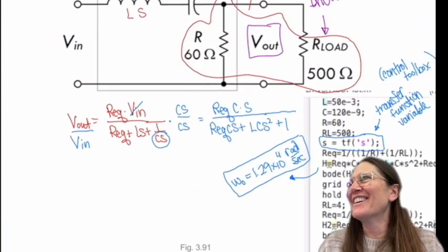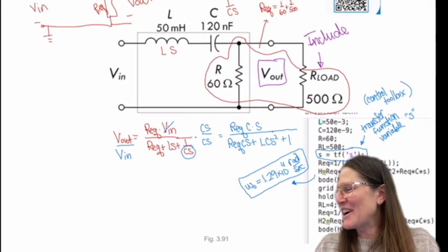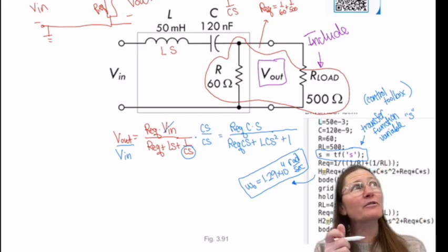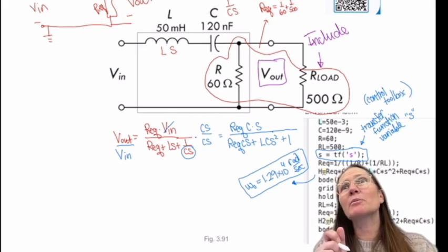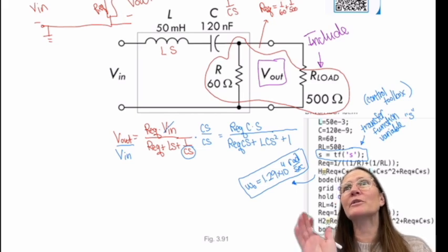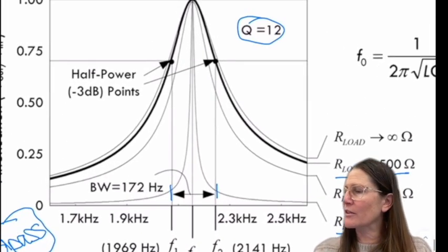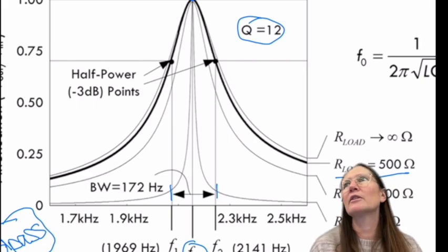So yes, you have to do some algebra in here. Also being able to identify where the critical frequency is, or that resonant frequency. So given this one, you would say this midpoint, and whatever that value is would be your resonant frequency.